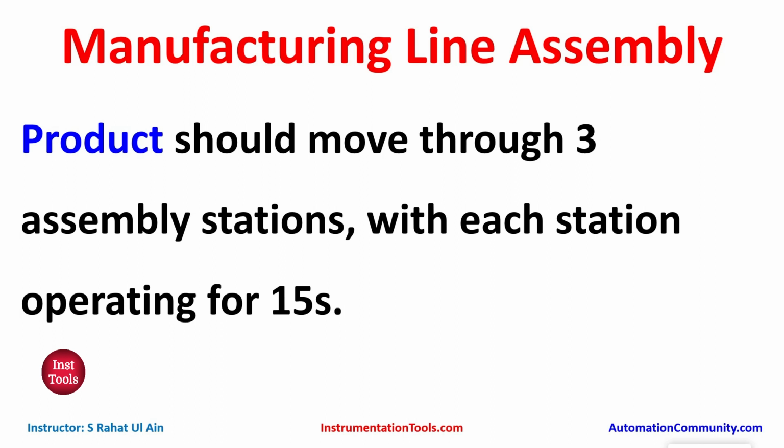So for this we will use a normally open contact for a start button. We will also use a normally open contact for proximity sensors. And then we will use some normally closed contacts that will help us to stop the conveyor belt system.